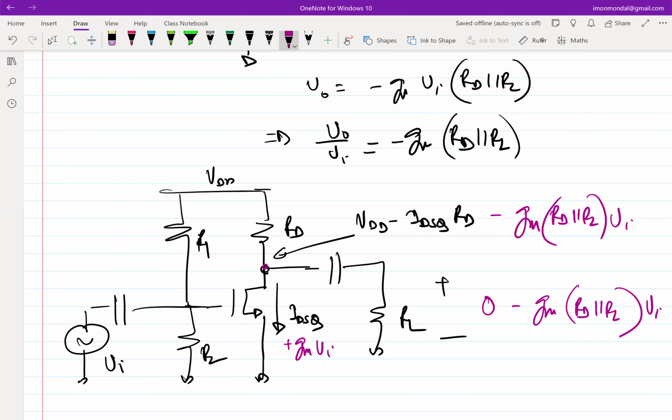So now that we know how to go about looking at currents and voltages, in quiescent, incremental, and total, the next thing obviously will be to figure out what the swing limits are, right? So you bias your transistor, the same thing that we did with regards to PMOS. The next thing will be to figure out how to size these transistors, how to size RD so that if I have 100 millivolts sin omega t, for example, the transistor remains in saturation and so on and so forth.